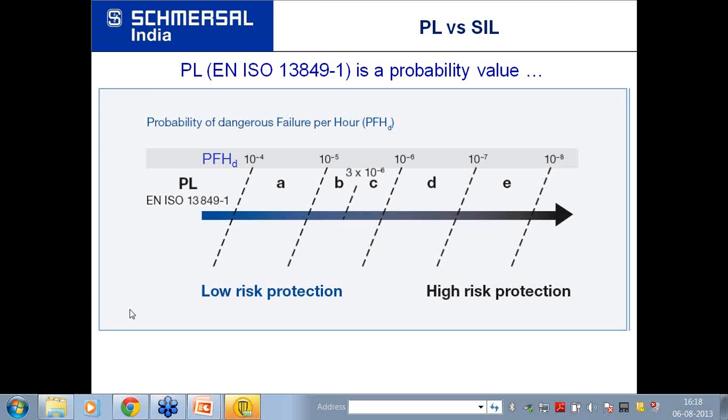So there we need to have a safety valve which is dual channel and which can take a feedback, so that in case of a failure in the system, it makes the system fail safe. So even for pressurizing equipment, the same safety and control systems will apply. Only the products will vary.